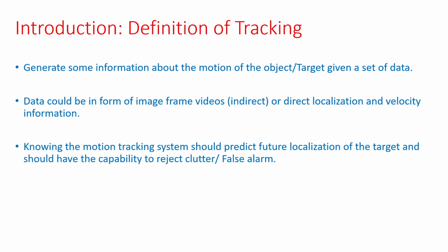Acceleration is not a part of tracking, but at least position and velocity. Position is the main thing for tracking, because you want to know the trajectory in an XYZ format. However, velocity is also an important part, as well as your turn rate, yaw rate, or heading. The yaw rate or heading is actually derived from Vx and Vy, from your velocity estimates, but it is also an important maneuver forcing function. A target can move in a straight line, it could go in a turn, or it could accelerate. So the acceleration forcing function could be your yaw rate, or, for linear acceleration, your Ax, Ay will come into the picture.